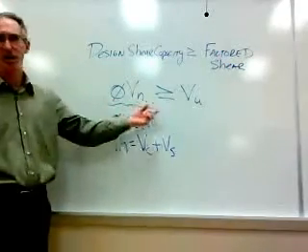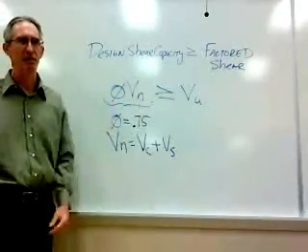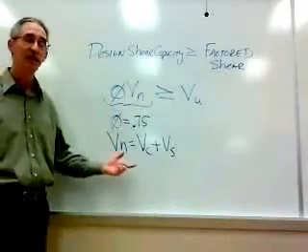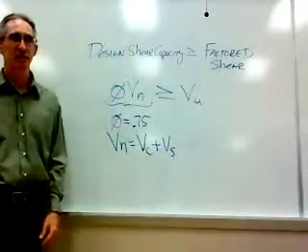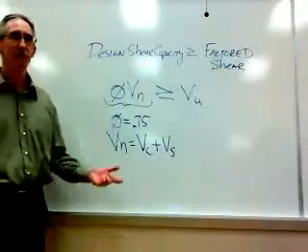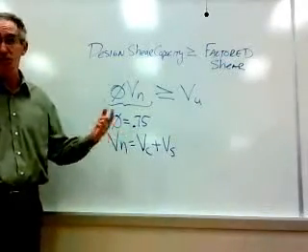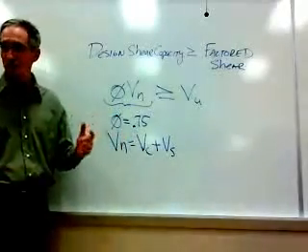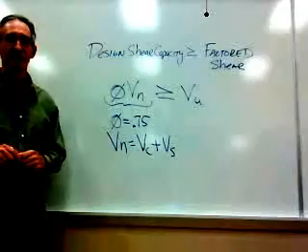We have a design shear capacity, phi V_n. Phi is just given to you. V_n is made up of two pieces. One piece is called V sub C, shear strength of the concrete. The other one's V sub S, shear strength that the stirrups provide. All right?